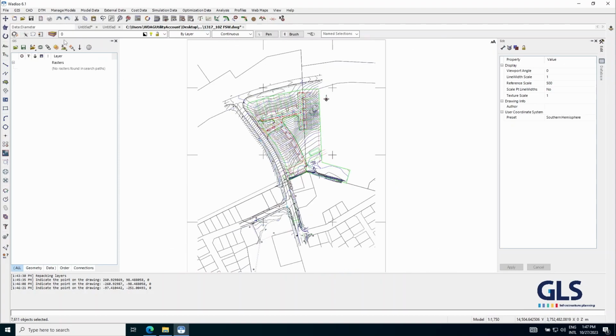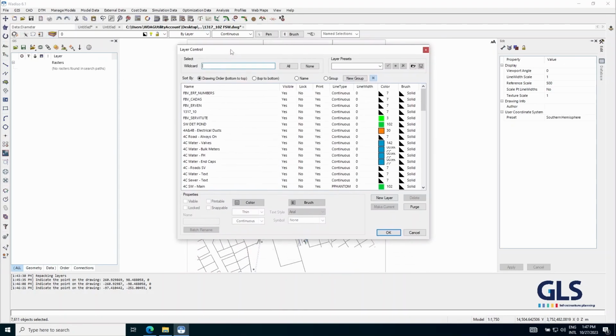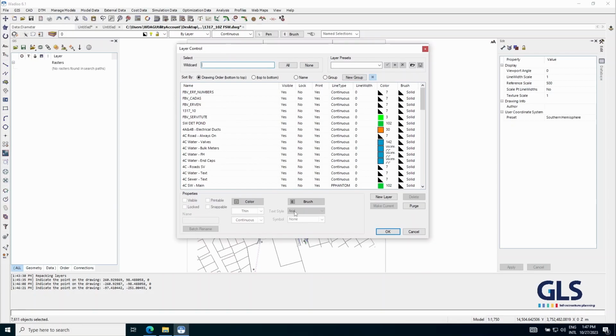Inspecting this information, what I want to transport, because I'm happy with the previous fixing of coordinates, we know the cadastral is all fine, so I am not interested in anything except water. I want all the layers that have water. I've inspected this prior, and I know all the water layers are fine. That's what I want.